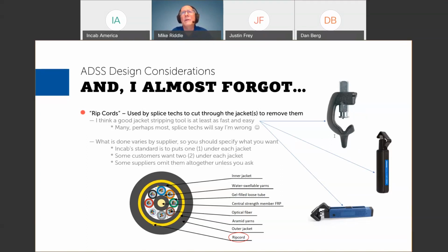And even then, the messenger cable would effectively ground out the field at that point. I'd have to do the calculations to verify what I'm about to say, but I think you would find that the lashed cable would end up in a lower space potential and therefore not subject to tracking.